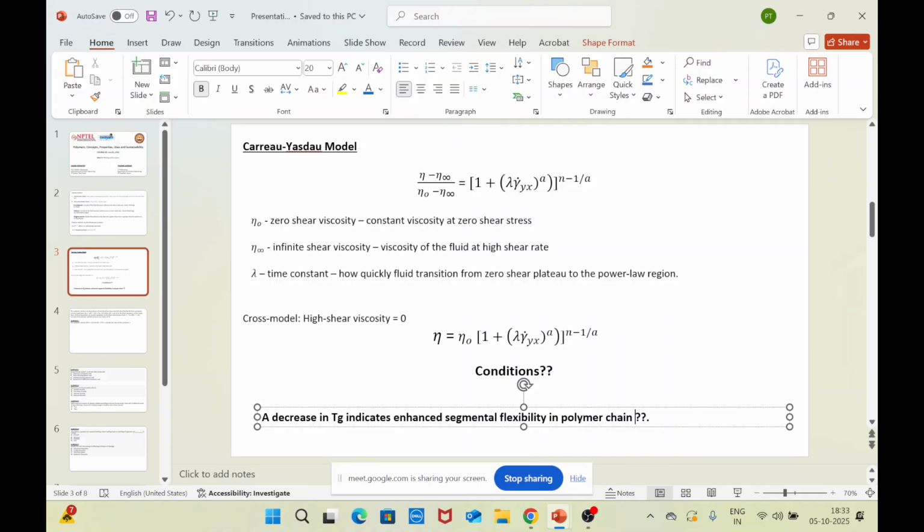So, how much can a polymer swell? What are the parameters that usually decide how much of the solvent can enter inside a particular polymer or polymer matrix? That typically depends upon two factors. One is your osmotic pressure. The solvent usually enters into the polymer, which is affected by the osmotic pressure, and then there is another opposing factor, which is your chain elasticity.